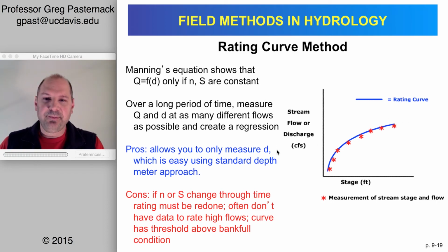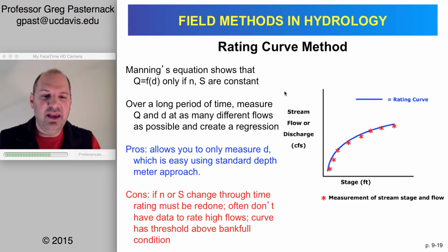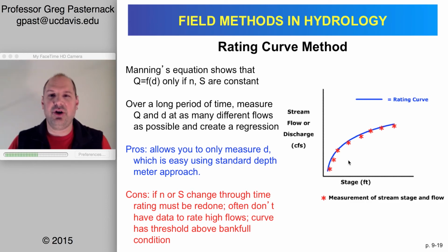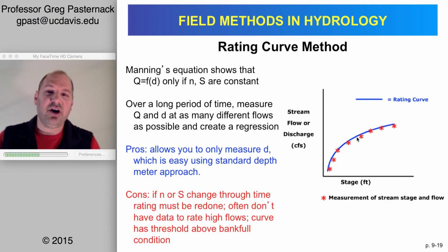So overall, whether you do it theoretically or you just go out and you measure a rating curve, and I should say that with a measurement method, the reason for doing that is it's very easy to have a pressure transducer or like depth sensor of some kind in a stilling basin on the side of the river, so that you're always measuring change in stage. And then you'd only have to go out, say, 30 times a year and measure discharges at a wide variety of flows, rather than trying to measure discharge all the time.